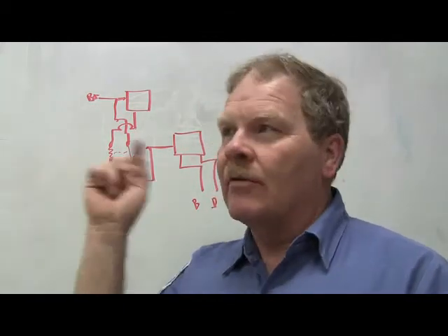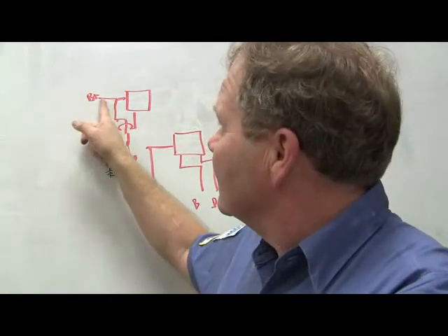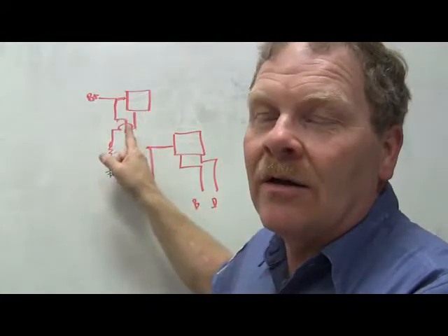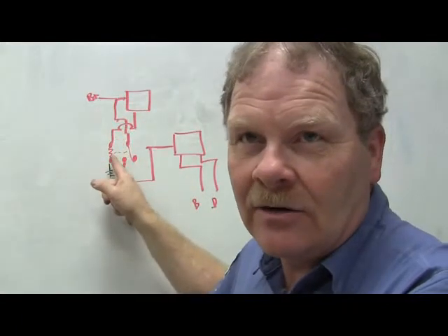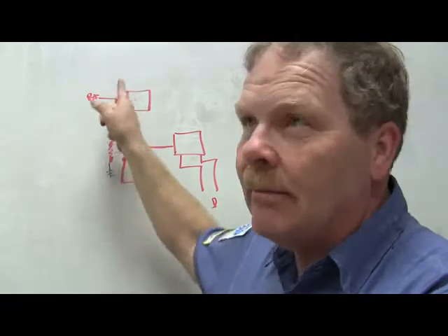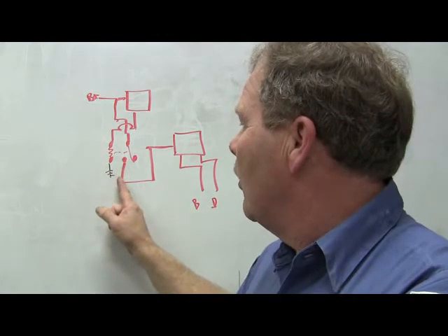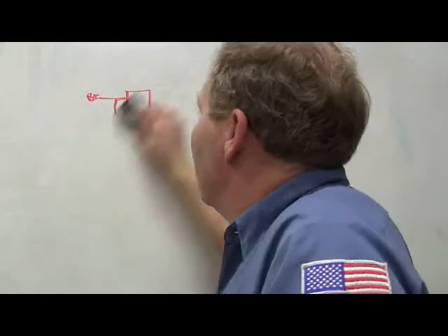And so what I would do is right up under there at the brake pedal, I did something very similar to this. I would actually take it so that the stoplight switch was closing a relay, and the power that used to go through the stoplight. See, the stoplight switch has still got to be getting power, because it's going to have to send power to the relay coil. But I would pull hot power from before the stoplight switch and let it feed the common terminal and let the normally open terminal go out to the lights. And the only deal was when they mash the brake, they hear a relay click, but nobody was bothered by that. You got me? Okay, so remember that.